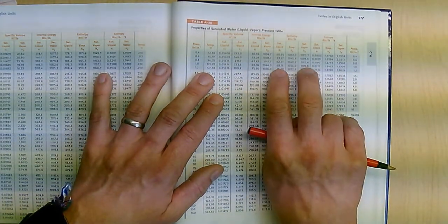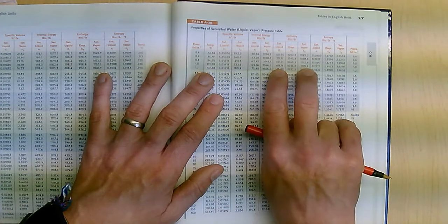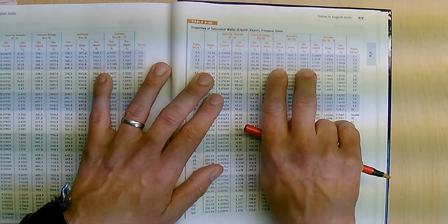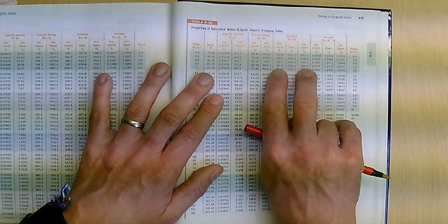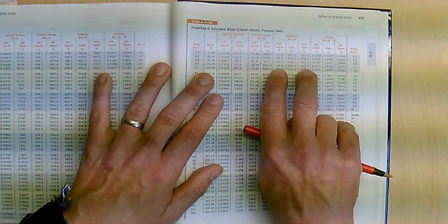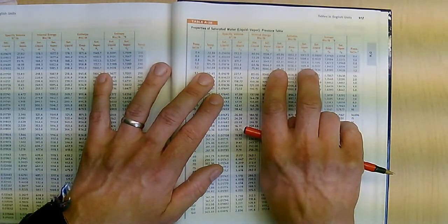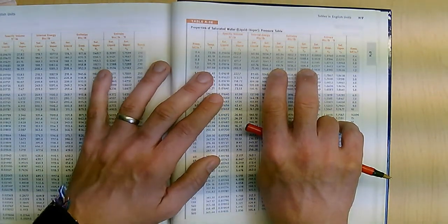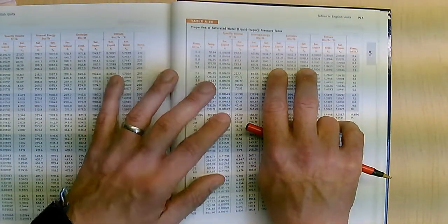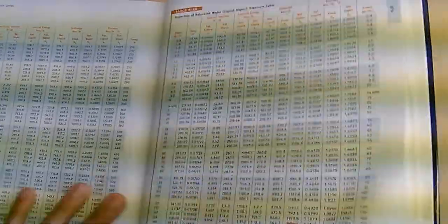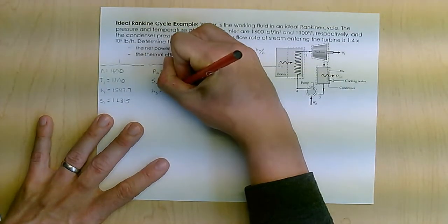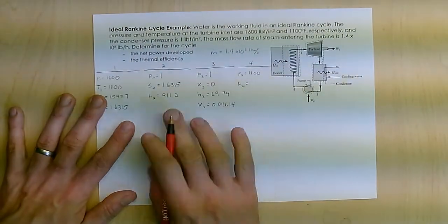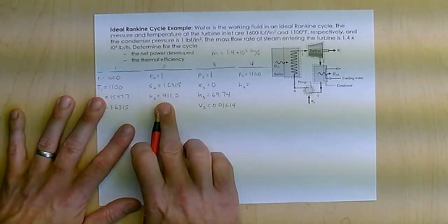That means I'm somewhere in between on the enthalpy as well. I can find the quality and calculate my enthalpy, which is going to be somewhere between 69 and 1105, probably much closer to the 1105. When I do the interpolation, I get 911.2. That's because I'm partway in between saturated liquid and saturated vapor at state 2.